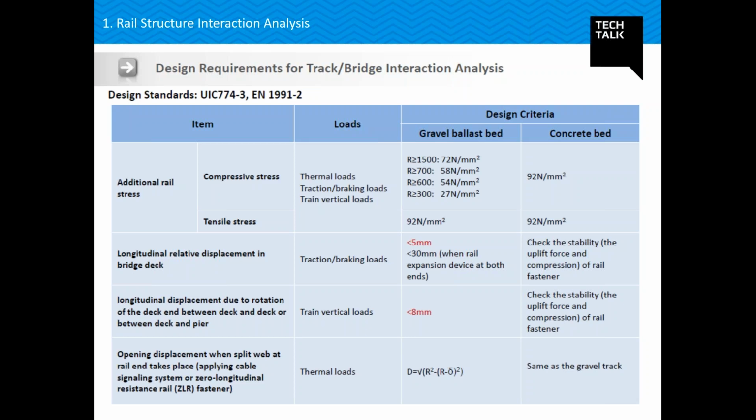However, in metro projects coming up these days, they have a concrete bed. Specifically for ballast bridges, if these serviceability conditions are breached, the stability of my ballast is compromised. So to ensure the stability of the ballast, we need to satisfy these serviceability criteria.